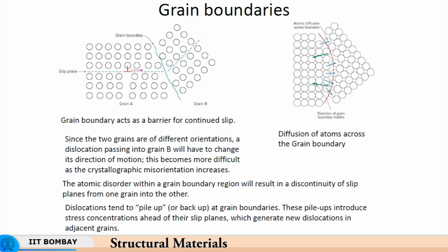Now, as the temperature rises and reaches above equicohesive temperature, the grain boundary becomes weaker because of diffusion, and the diffusion results in weakness of the grain boundary. So, grain boundary is more easily deformable. So, what happens is the grain is stronger than the grain boundary.